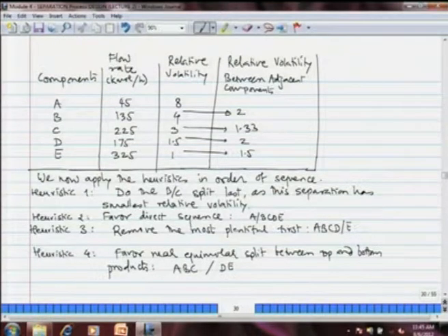In this case, we have to apply other practical constraints, or other considerations like how corrosive or heat sensitive the material is, and so on. We have to choose any of these sequences, and then reapply the heuristics again. So, we start with one decision here, like we say that we favor direct sequence, we remove A from the BCD mixture, so that we do not require refrigeration or high pressure in the subsequent columns to condense A. After removal of A, we are left with the BCD mixture, and then you apply the same sequence of heuristics for the BCD mixture and proceed.